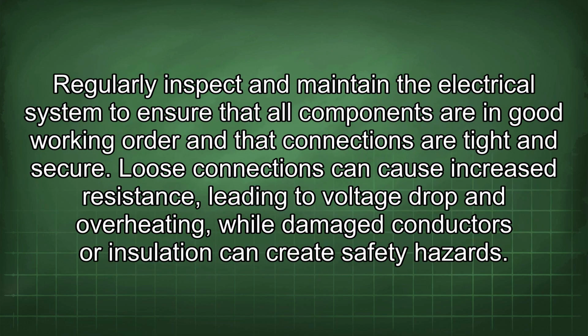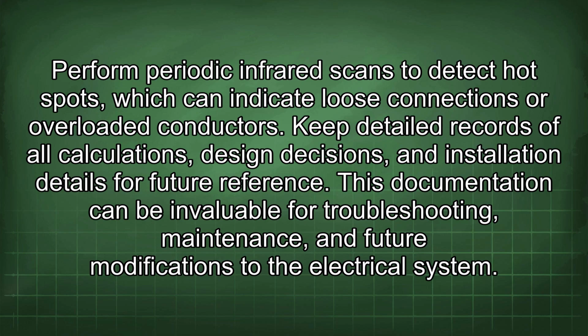Regularly inspect and maintain the electrical system to ensure that all components are in good working order and that connections are tight and secure. Loose connections can cause increased resistance, leading to voltage drop and overheating, while damaged conductors or insulation can create safety hazards. Perform periodic infrared scans to detect hot spots, which can indicate loose connections or overloaded conductors.